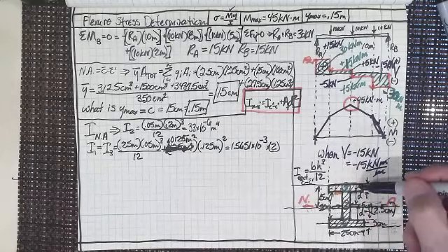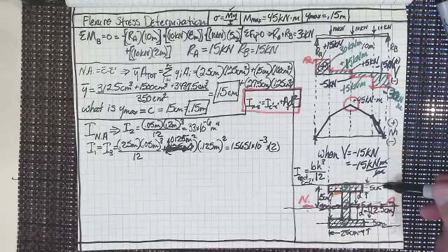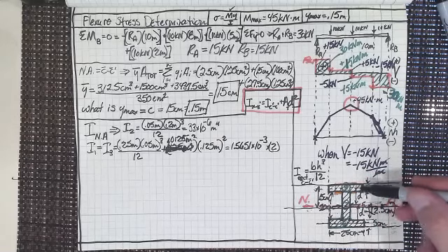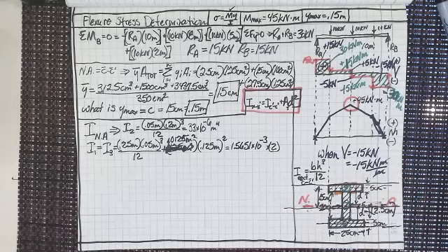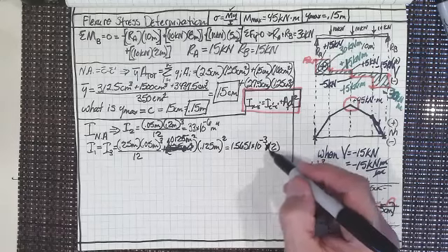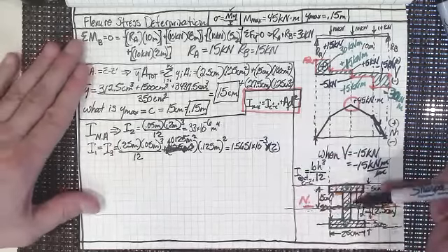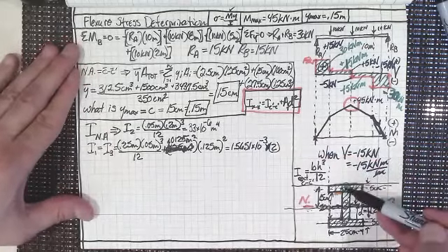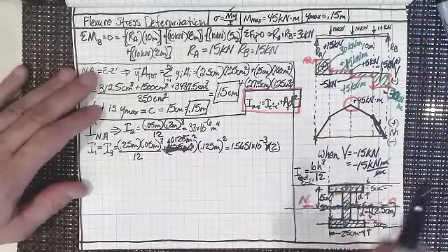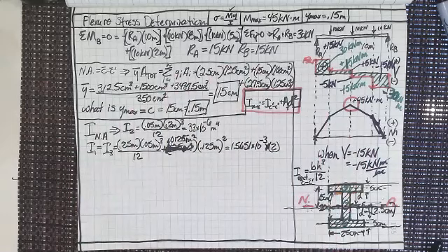Because we've got 3 and 1, which are exactly the same distance away, and we found their centroidal axis, the moment of inertia about their centroidal axis, and about this centroidal axis, and now we've transferred that to the center. So that's got to be times 2, because I1 and I3, of course, are much larger contributors to this than the center. So let's add all of those up. I want to make sure that those come to the same answer that I have here, where I missed all of these steps.